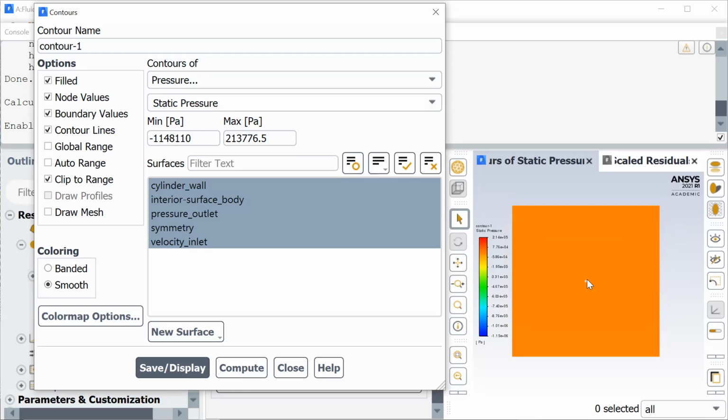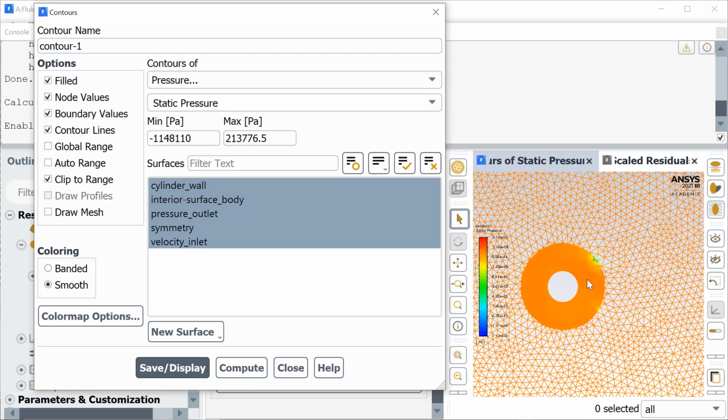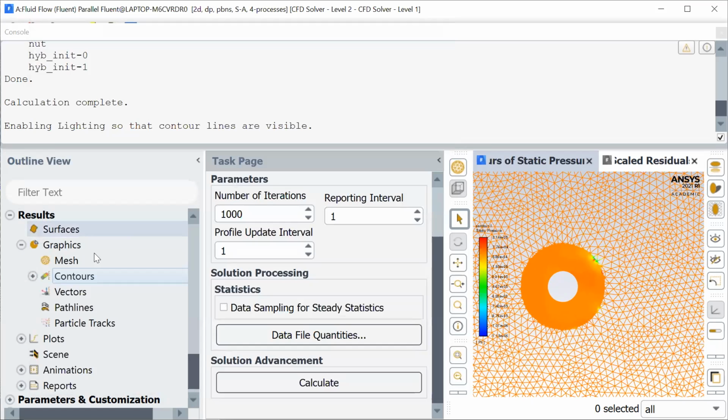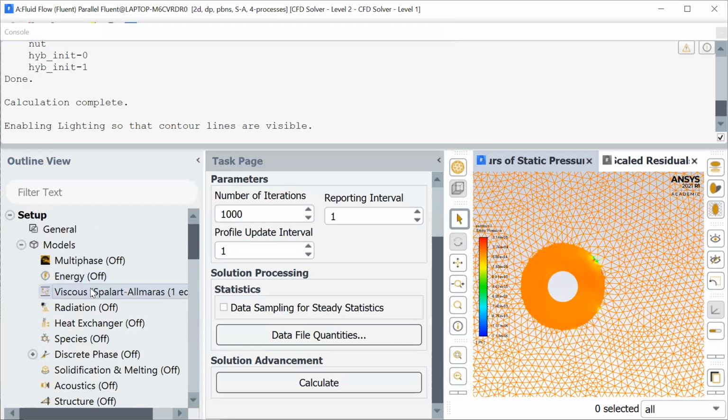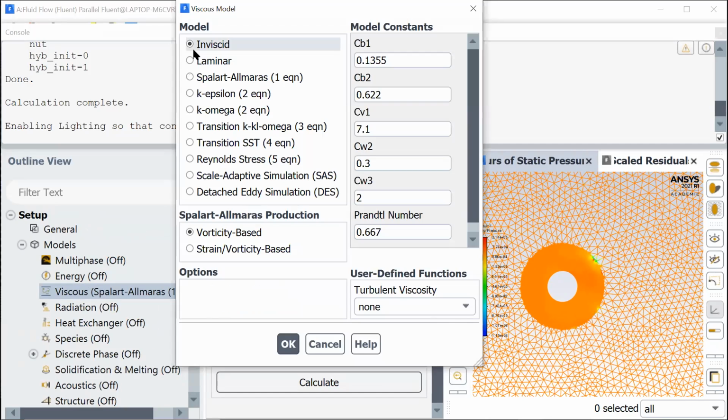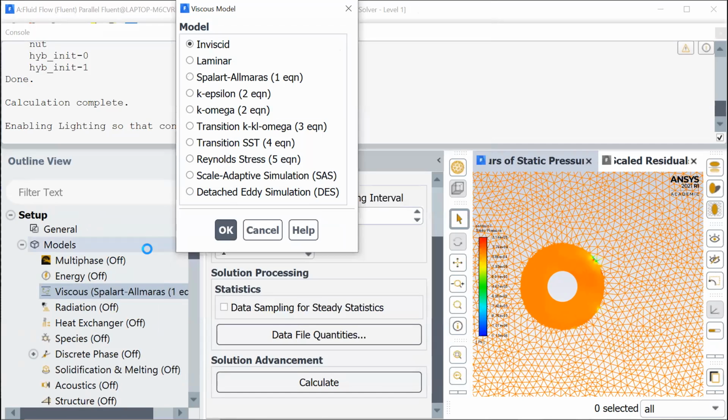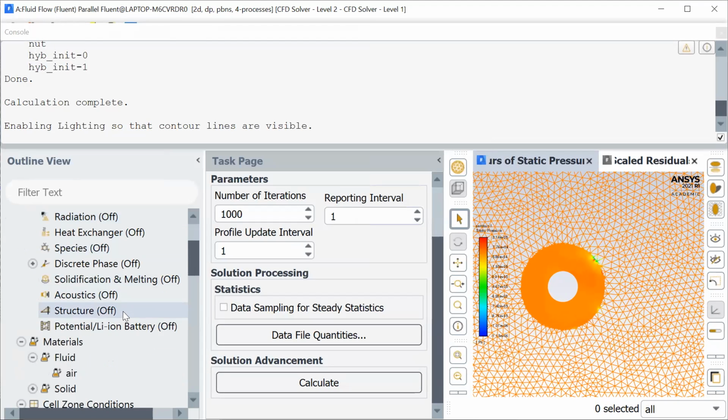Yeah, we have some major issues, it looks like. These are not accurate. We've got incredibly high pressures, and that makes sense with that high residual. It seems like there's an issue. I may need to relook at this, because this is definitely not a good result. Let's go ahead and check our inviscid flow and see if we get results that are a little bit better.